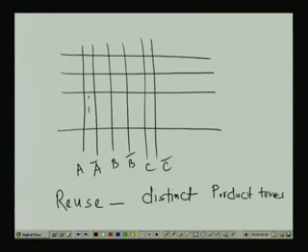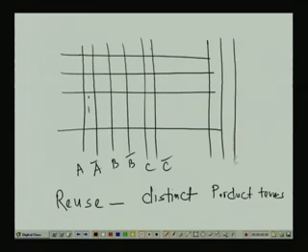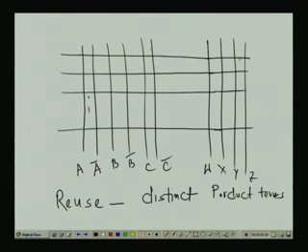So, that means only the product terms for, say, all m outputs. Say if I have 4 outputs, w, x, y, z, then one product term can be shared by each output, and this we are calling the reuse of product terms, or reuse of min terms.